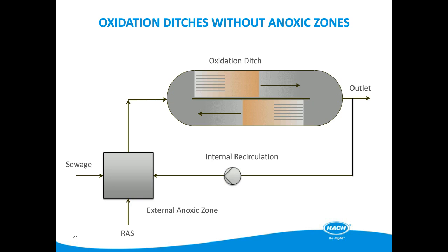The next question is: do you have any further advice on controlling foaming filamentous bacteria? Yeah, that's difficult. The use of an anoxic zone and selector zone is obviously the way most of this is done. Keeping filamentous bacteria under control is quite an issue in some sites. Low DO can also tend to promote their growth. There are many things, depending what type of filamentous bacteria you have there.